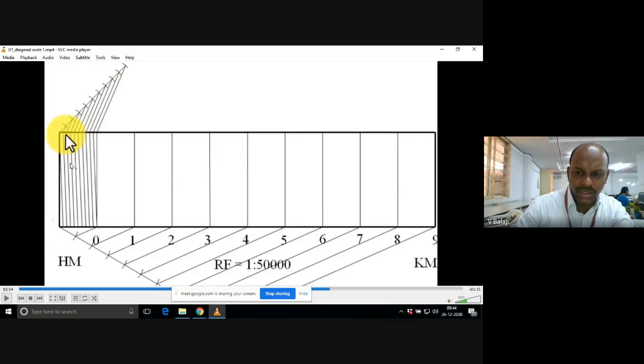So what about decameter? To represent decameter also in the given scale, we already took this height of 4 or 5 centimeters. Again we need to divide this height into an equal number of parts. Now you need to see the relation between hectometer and decameter.